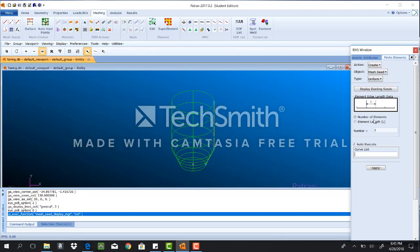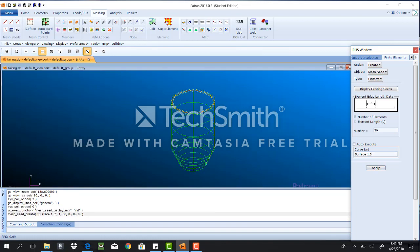Then we'll go to create mesh set, type uniform, the number 36. In the curve list, we select the surface 1.3, which is the one at the top, and then apply it.